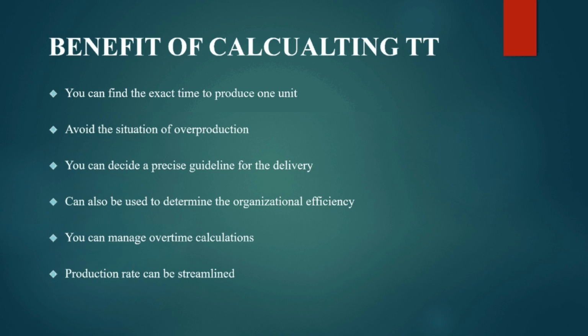So with this calculation, you can decide how your line should be, at what rate your line should produce the parts, how many manpower are required to achieve that takt time, then how to have a single piece flow, what should be the layout of the plant, what time the logistics should be planned, what time the truck should come, how many material handling systems are required. So with takt time as the baseline, your plant will be running.